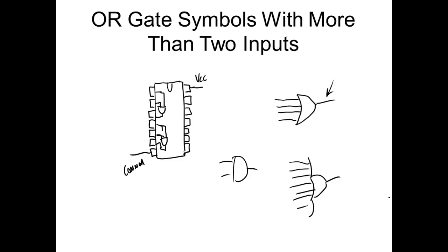Y'all understand? I got 14 pins to work with, guys. I've got power. Each one of these gates could share the same power, just like your house, right? You got one panel box. The only thing they have in common is they're in the same package. So we could have up to 4 in there. If I went to 3 inputs, then it would require 4 pins, and I could have 3 of them in there, right? Up until the maximum of 11. That's the maximum we can have.